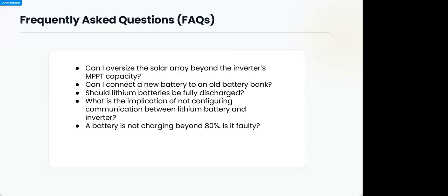That is it. So this was done to avoid you saying, I just want to put 3,000 watts, which will limit the system to a point where, early in the morning, because it's very low or the weather is bad, you can't get more energy. So that's the advantage of having more panels and then increasing the capacity of your solar panels slightly beyond the rated capacity of the charge controller.